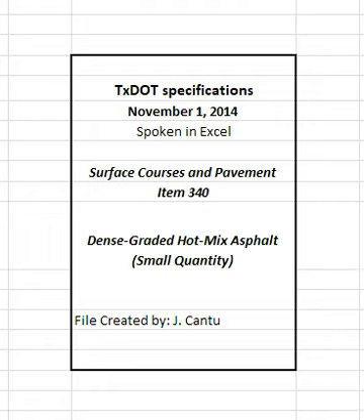Control the mixing time and temperature so that substantially all moisture is removed from the mixture before discharging from the plant. The engineer may determine the moisture content by oven drying in accordance with Tex-212-F, Part 2, and verify that the mixture contains no more than 0.2% of moisture by weight. The engineer will obtain the sample immediately after discharging the mixture into the truck, and will perform the test promptly.